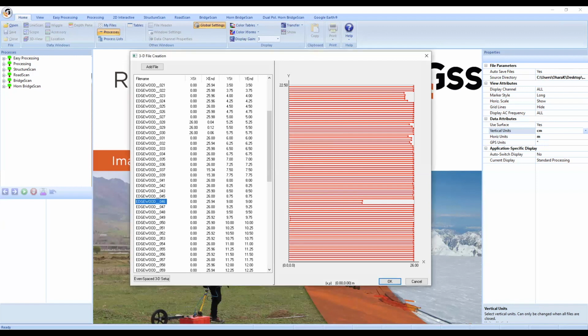We're making note of the dimensions, right? Very critical. You need to know how long these lines are. We're making note of which files are in this grid, files 7 to 100, how many profiles there are, 91, how many add-on lines there are, files 38 and 40 are the add-on lines, and then which ones need reversing. It also helps to know why you're reversing them. Not critical, but it does say that there was a gravestone. That's why we reversed these 3.